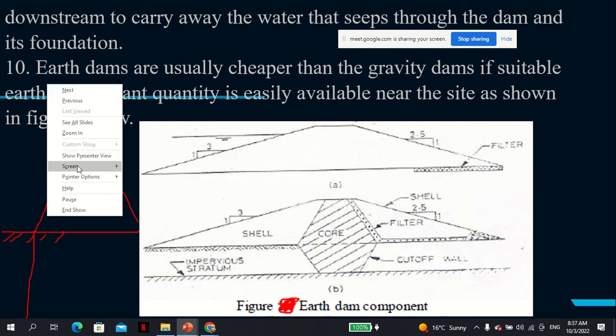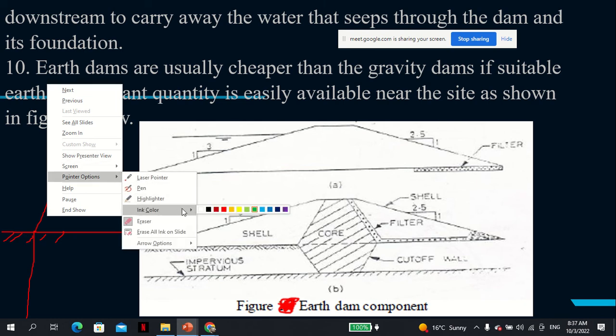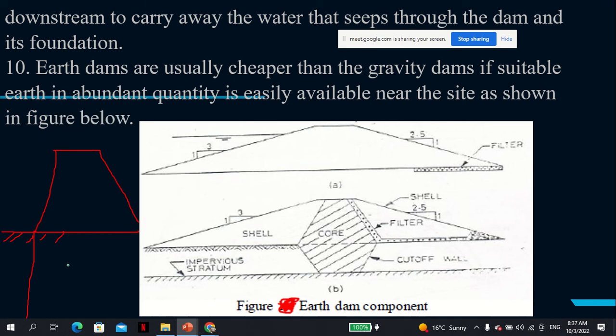But if you put a sheet pile, then you increase what is called the drainage path, so water will go down, and so the permeability will reduce. That's the point. You can use a sheet pile. You can use a combination of sheet pile and grouting. That's what we are saying. So when we have impervious strata, then that's fine. But when you have pervious strata, then you have to increase the drainage path to reduce the permeability, I mean the ability of water to escape and endanger the embankment.